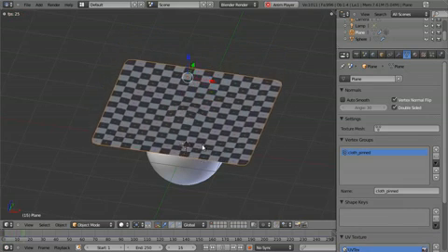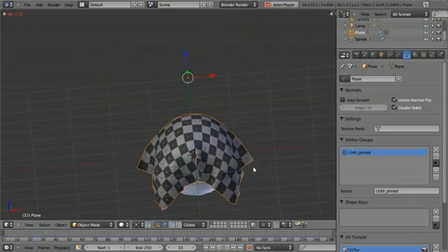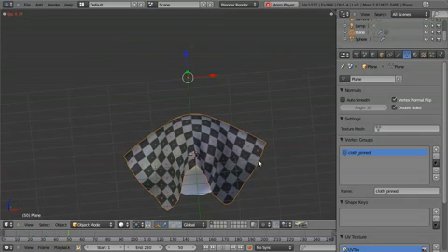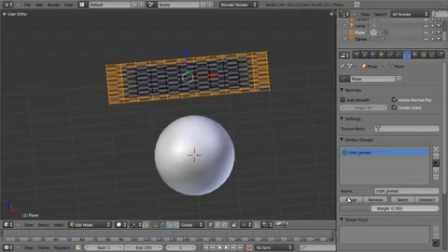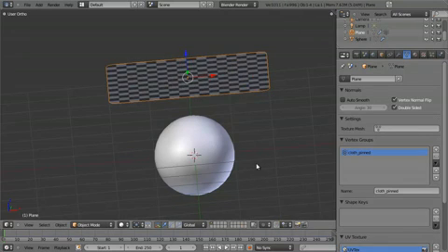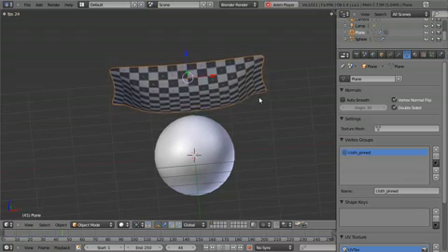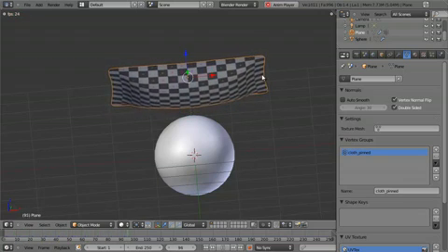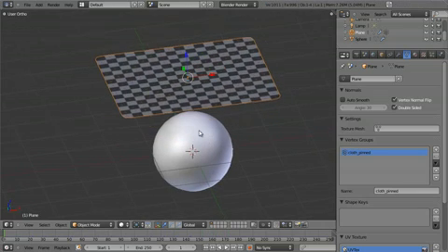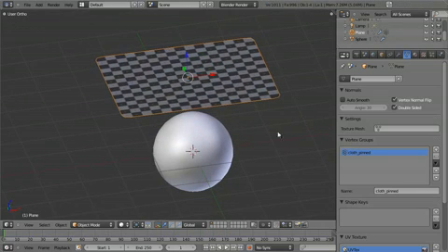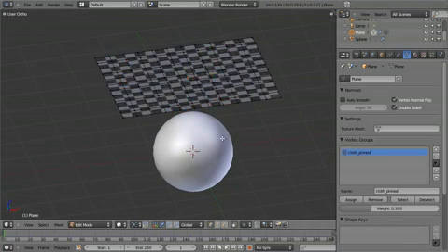And now if you hit Alt A, those corners will be a little heavier or will have less simulation applied to them. And by the amount of weight, you can determine how much that is. Now note, anytime you change the weight, you need to click assign. So now you'll see how it's kind of folded back on itself. Now obviously in this case, it's like it's been held in place. So you need to play with that, but you can see how that could feasibly be used.